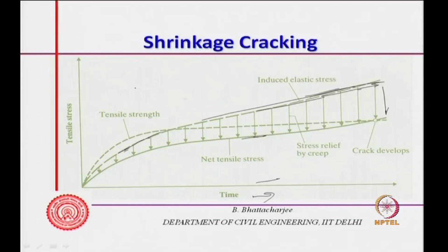So, basically where curing is not proper, this scenario is seen much, particularly in the hot dry desert sort of climate where relative humidity is very little, or in a composite monsoon climate during the hot dry desert season. So, shrinkage will increase with time, tensile strength also increases with time, but since it is sustained and restrained, there will be some relaxation.